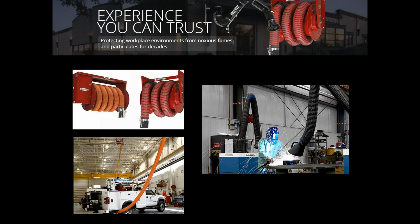Number one, it is the most effective way of protecting the breathing zone of the worker, right? So that's job one. Number two, in general, it is the least expensive solution because our capture is focused at the point of exhaust creation. We don't remove a lot of air from the room. So in general, a source capture solution is going to be less expensive than general air ventilation and the makeup air that comes with those types of solutions.